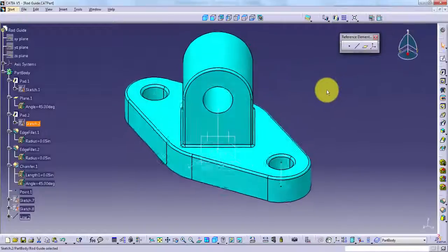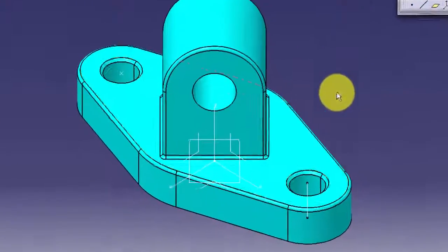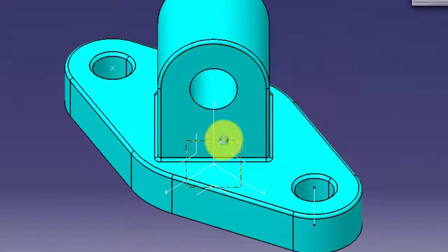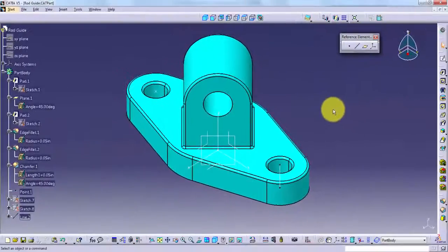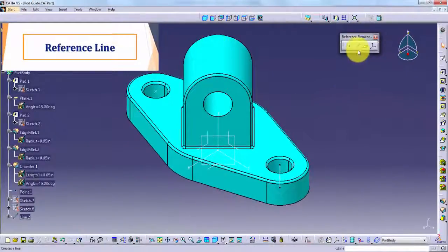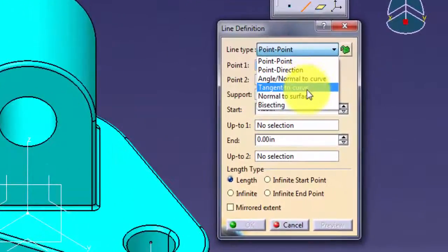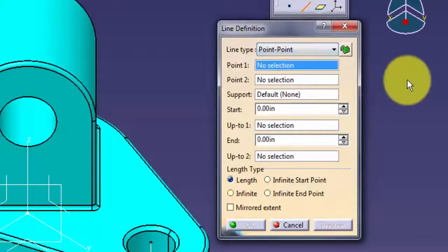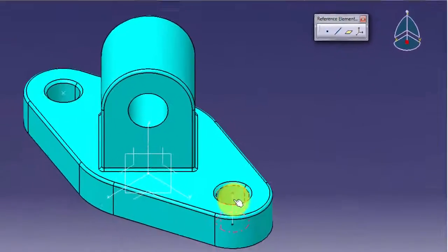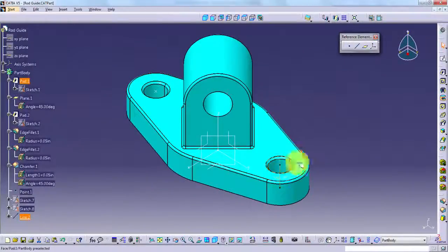Reference planes are infinite in size. The display that you see in the graphics window serves only as a reference, and to allow for the selection of the feature. A reference line is a feature and object that represents a vector in space. You can define a reference line using 2 points or a single line or edge. Reference lines are commonly used to define the reference direction of a feature. They also help to constrain a sketch or define a rotational axis.